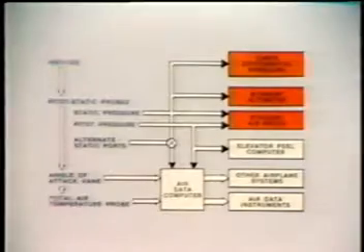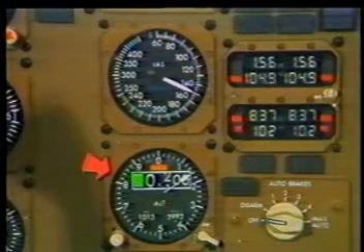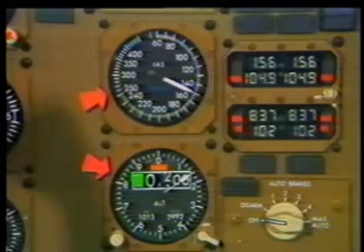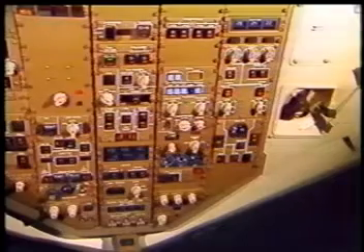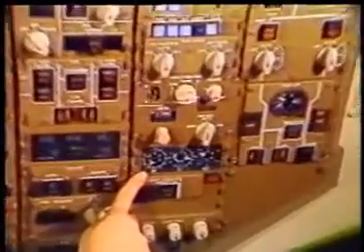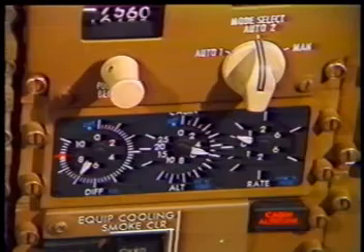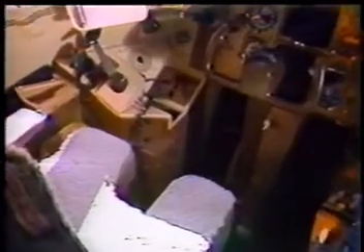The cabin differential pressure gauge and the 2 standby instruments for airspeed and altitude are located on the flight deck. The standby altimeter and standby airspeed indicator are located on the P1 instrument panel. The differential pressure indicator, which indicates the difference between cabin pressure and outside ambient pressure, is located on the P5 overhead panel.